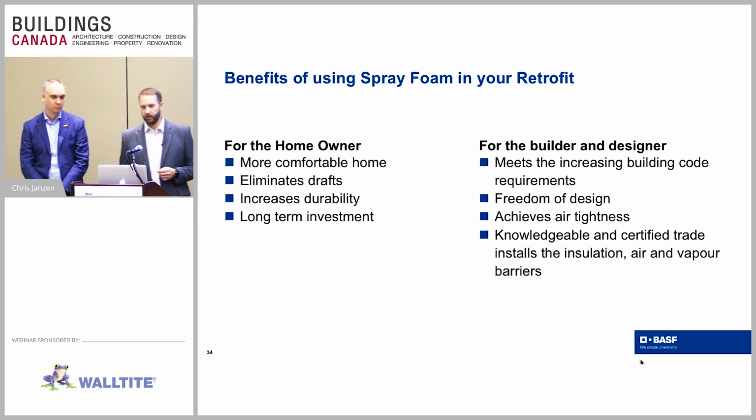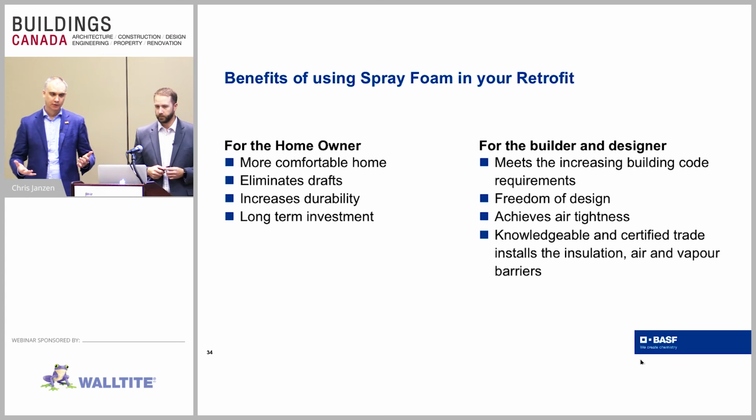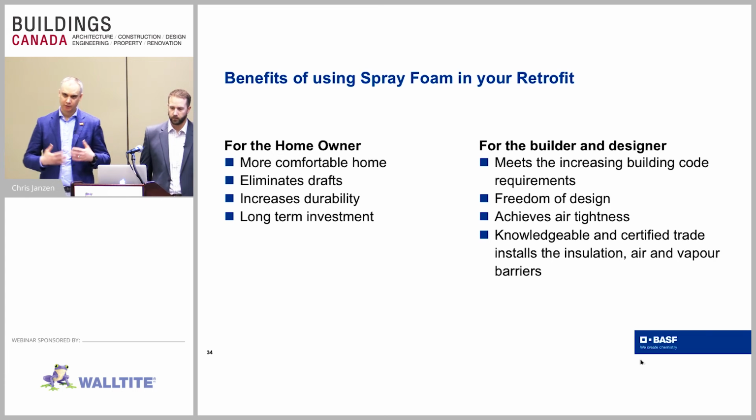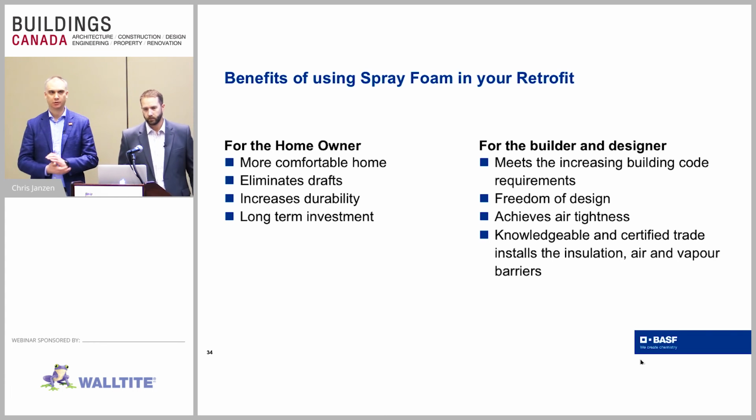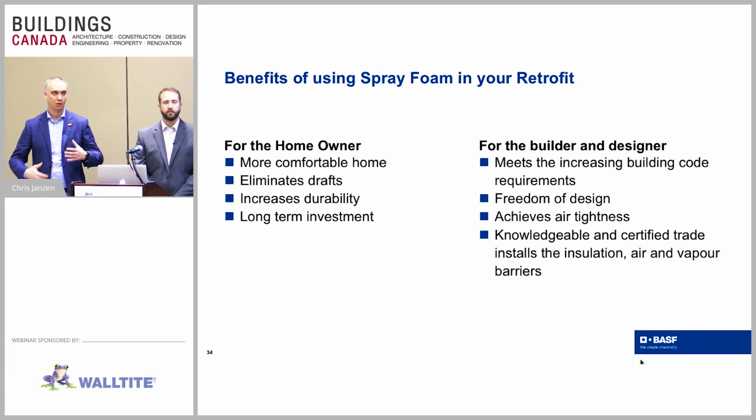Do you want to talk about the builder side? Yeah, so the building codes are changing. As you're doing retrofit, there's going to be changes in the retrofit code requirements as well, where you have to increase the R value, you're going to have to increase the air tightness. There's talk about doing mandatory blower door testing even on resale homes. So all this stuff, by addressing air leakage, is going to help increase the value of the homes.